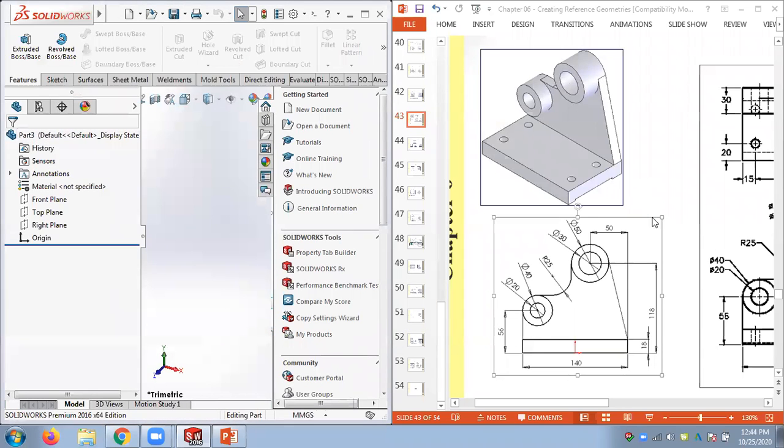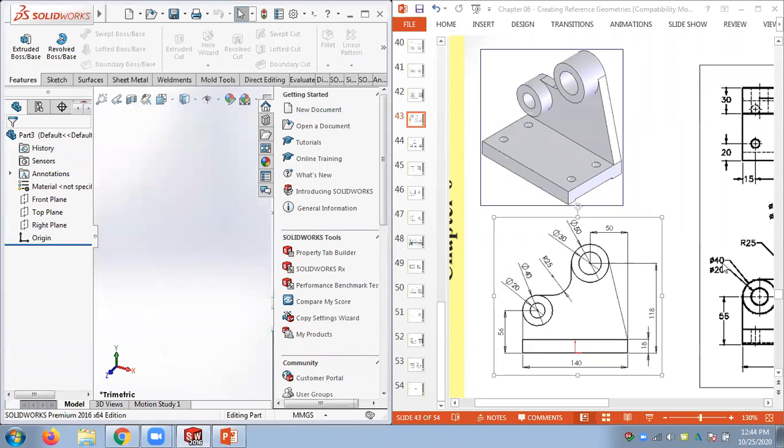So I have only removed these holes and this cut. Other things are the same. So you need to understand what to draw. Not everything given in the manufacturing drawing is needed. So if someone wants to manufacture this, he will not cut this first. He will make the model and later he will drill these holes. And later he will cut this groove. So that's how the manufacturing happens. So you need to understand that also.